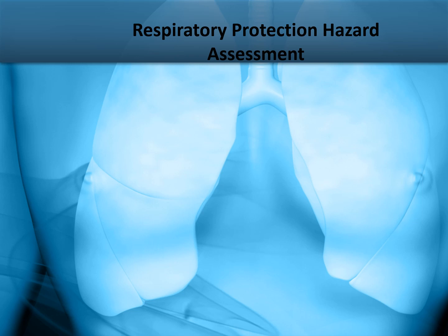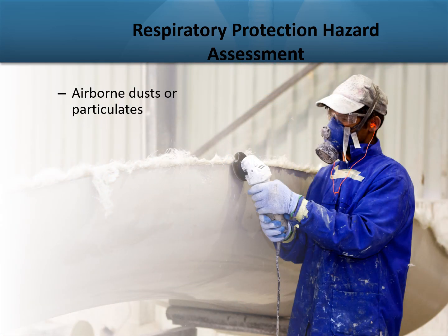Hazard assessments for respiratory protection evaluate the potential inhalation of airborne dust, fumes, or similar particles, which might come from grinding, cutting, sanding, or welding operations. Other dust might come from wood chips, grain, or other solid granular materials.